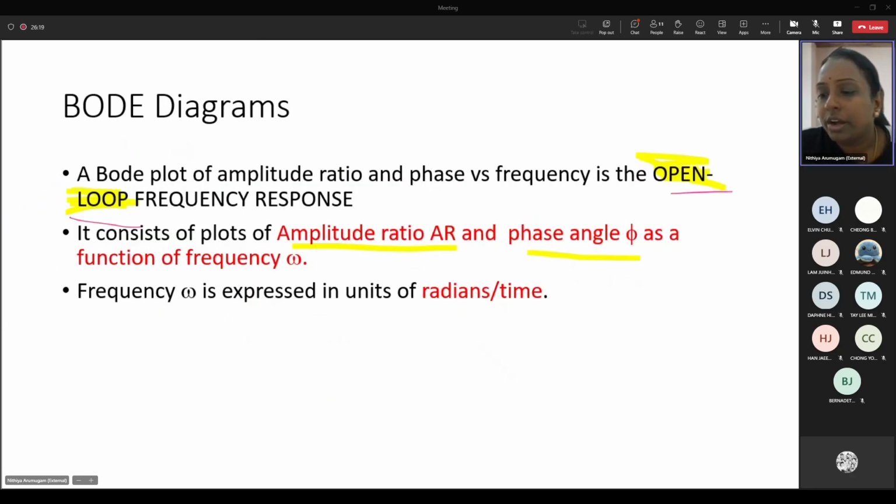Now, before moving into the Bode diagram, the dead time response is actually delayed for some time after the input makes its step change, right? So there's a period of time where there will be zero response following the step change signal, okay? So we can also call that transport delay, okay?